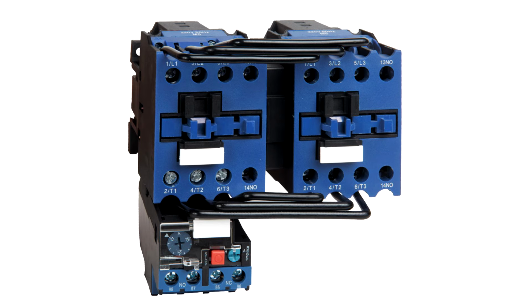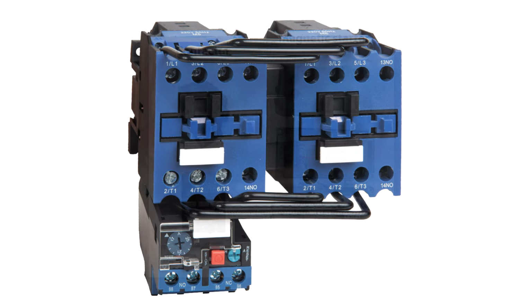According to IEC 60947-4-1, 2021, a contactor is a contact switching device having only one rest position, non-manually actuated, capable of making, carrying and breaking electrical currents under normal electrical circuit conditions, including operating overload conditions.